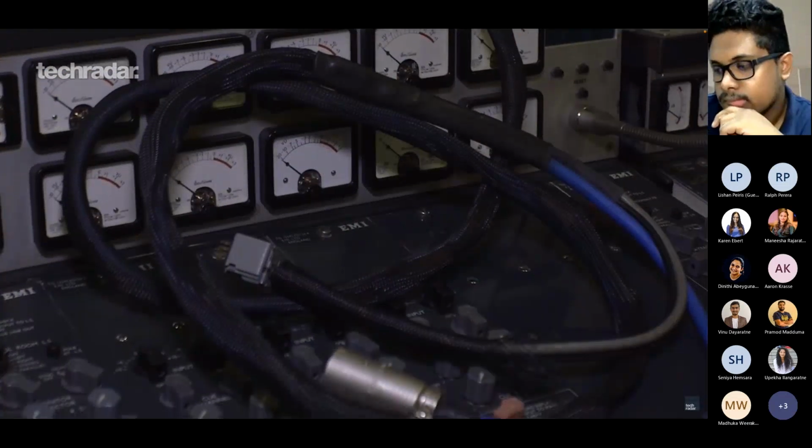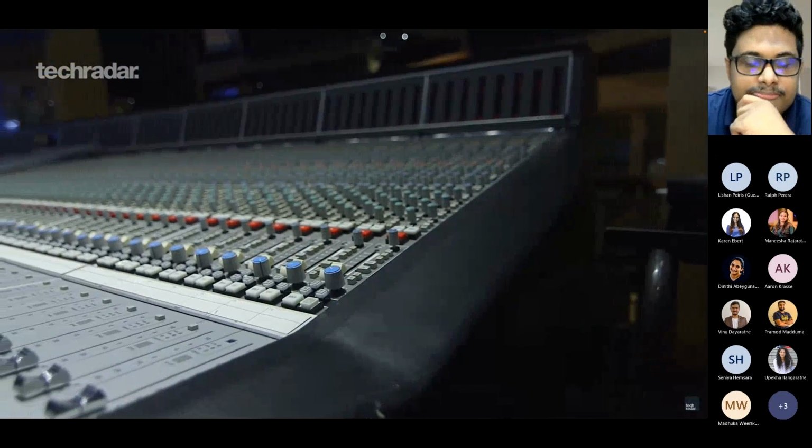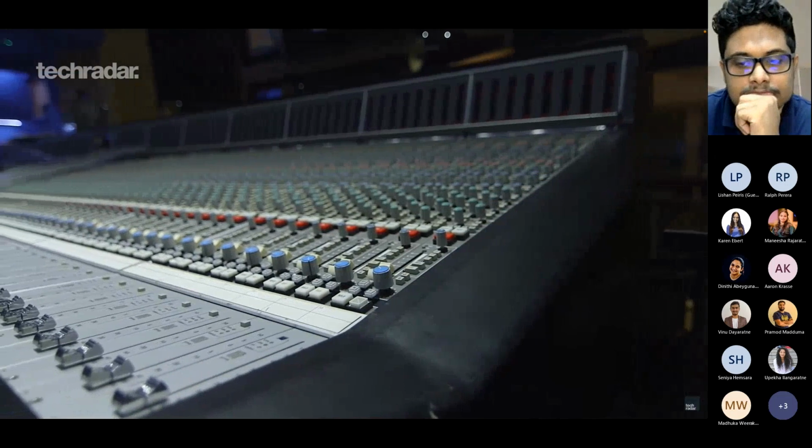The sampling frequency is the number of times in a second that you sample the level of the recording, basically. So obviously the higher the sample rate, the more detail you get in a second's worth of audio. And then the bit rate is the kind of depth of the audio. Let's say if you had 8-bit, there's 8 levels of volume really that you can get.